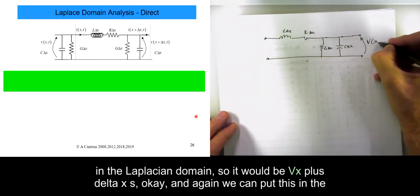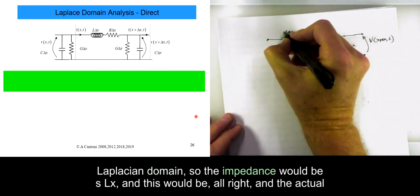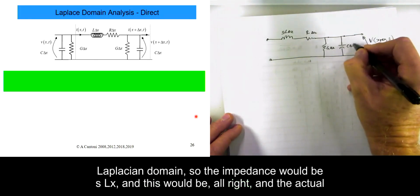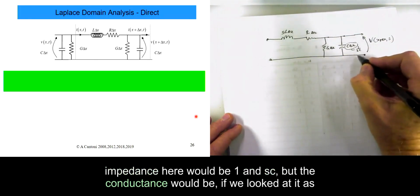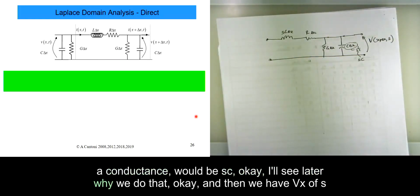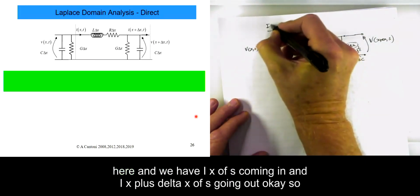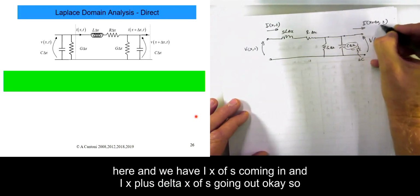So we have V at x plus delta x of s, and again in the Laplace domain the impedance would be sL delta x. The actual impedance of the capacitor would be 1 over sC, but if we looked at it as a conductance, it would be sC. We'll see later why we do that. Then we have Vx of s here, Ix of s coming in, and Ix plus delta x of s going out.